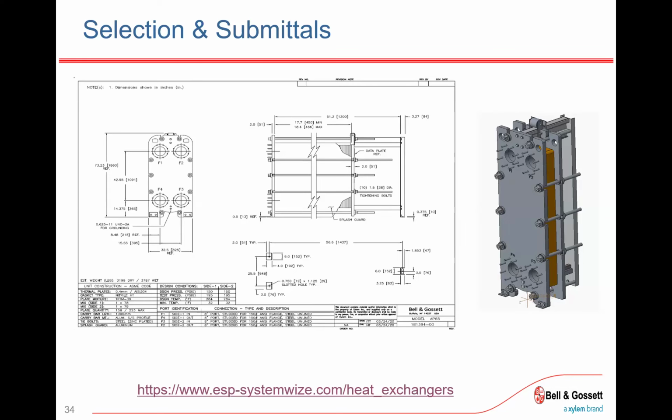If my design condition that's rarely achieved is at 1500 RPM, I like to obviously know the RPM, motor horsepower, and duty point efficiency is important. But I think George may have spoken a little bit about that part load efficiency value. So you have your duty point efficiency, and then it's rarely ever required off the top.